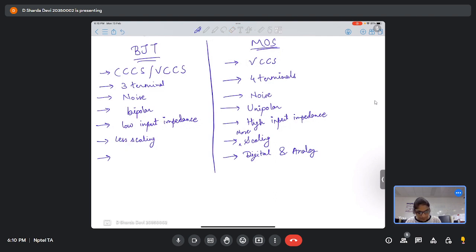What else? What more can you think of? Ma'am, in BJT there is thermal runaway, while in MOSFET there is no such phenomenon. But there are also effects like punch through in MOSFETs also. So we cannot say it like that. So let's leave it. What else? What else can you think of?